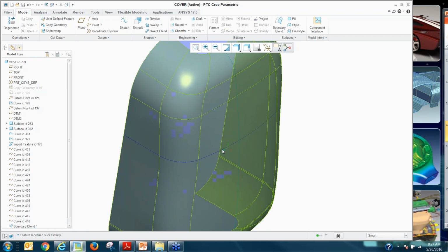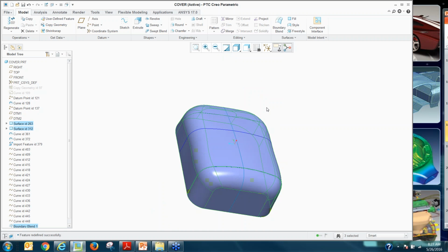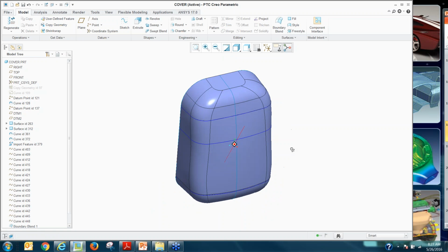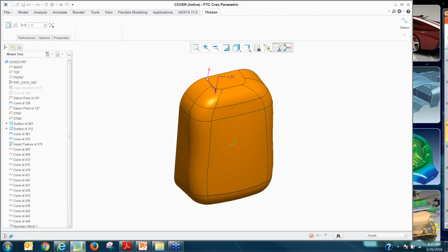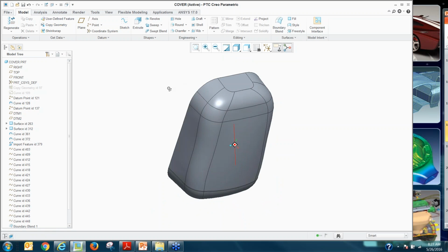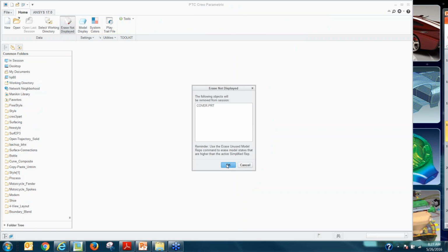And then you would ideally merge all these. You can merge any number of surfaces, and once you merge it, the next step is obviously to thicken this. You would go thicken it, add a thickness to it, and so that's usually the workflow on the technical surfacing, if you think about it. So whatever I showed you is the technical surfacing side.